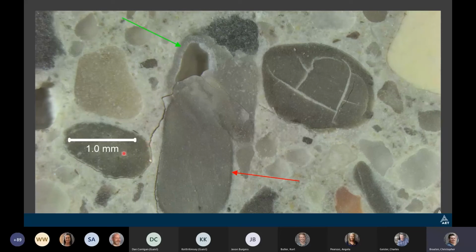Now, these sand fine aggregate shale particles aren't going to really do much damage to your concrete at depth. But if they are near the surface of your concrete, they can start to cause those pop-outs. They can start to cause pop-outs because of freeze thaw, because they're so absorptive. They can also cause chemical pop-outs, which is ASR induced pop-outs. And that is actually called near surface alkali silica reactivity. And I'm going to touch on that in a little bit.